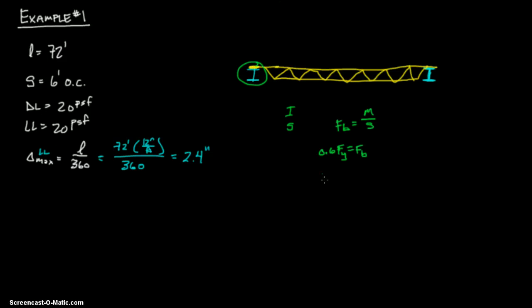So let's say you have 50 KSI times 0.6 equals, what, 30 KSI. And therefore, if you have a moment of, let's say, 15 foot kips, then you would have to go in and make sure you get an M over S that's less than this 30.